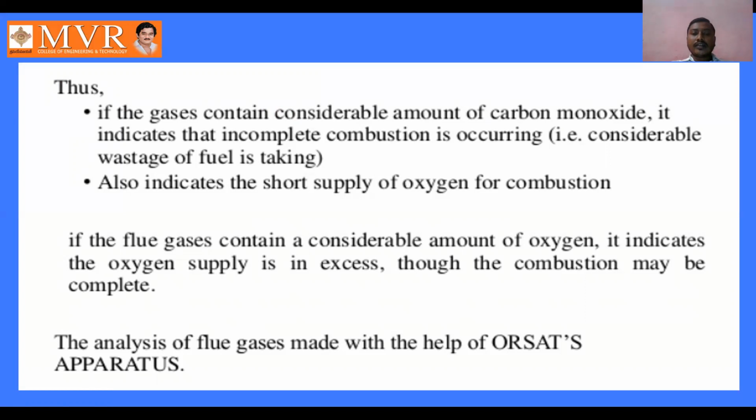If the flue gases contain a considerable amount of oxygen, it indicates the oxygen supply is in excess, though the combustion may be complete. If we give more oxygen for the combustion process, the combustion will take place very quickly and be completed.